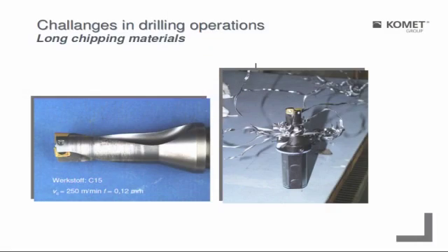So what happens in the drill? When you look at such a drill, we see the clearance around the tool, we see the swarf inside and outside, and the noise will be, you have heard it already, like this. It's a torsion vibration coming up. But when we find this situation, that the chip spirals and the chip flutes are filled up with swarf, then the noise will change from this sound into this sound.